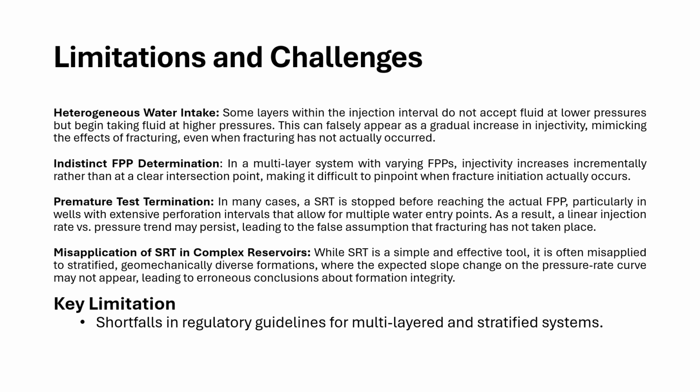There is also the occurrence of premature test termination. In many cases, the step rate test is stopped before reaching the formation's parting pressure, particularly in wells with long perforated intervals. In these wells, the long perforated intervals allow for multiple entry points of injected fluid. And as a result, a linear injection rate versus pressure trend may persist, and that may lead to a false assumption that fracturing has not taken place.